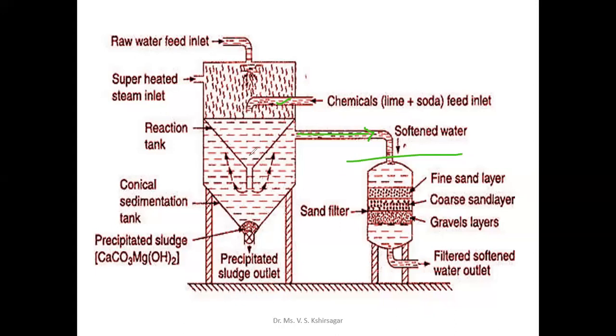So here we have provided reaction time in a reaction tank, and when it is slowly falling down, obviously the solid particles will settle down at the bottom and can be removed from the bottom. And the clean water will rise up, and that can be removed from the top.